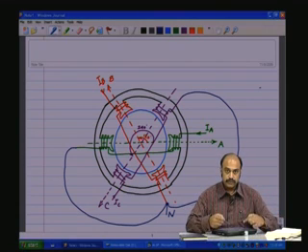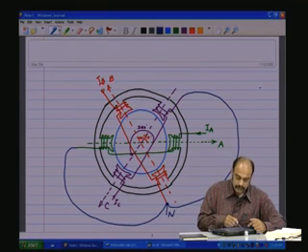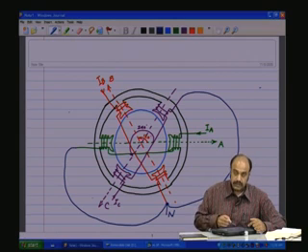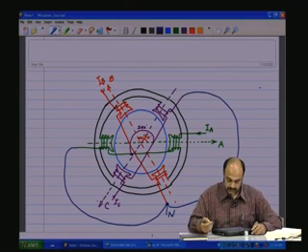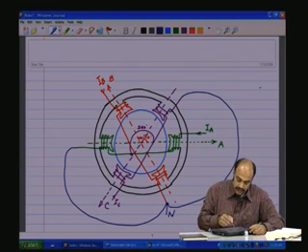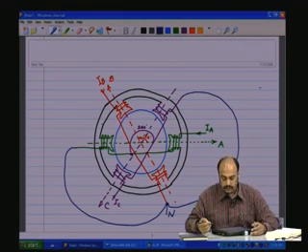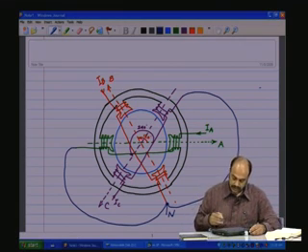So we have the three phase currents, 120 degrees electrical in time, that is when this is at 0, this is negative, this is also negative, like in a three phase current. So the amplitudes here along these three axes vary according to the time. Let us see what happens to the amplitudes of the flux.